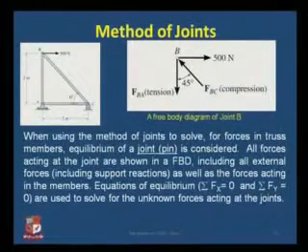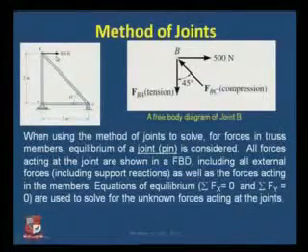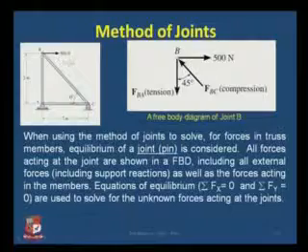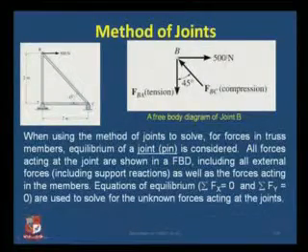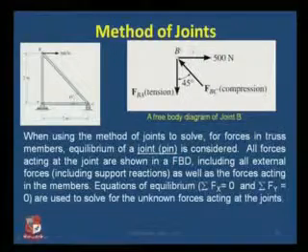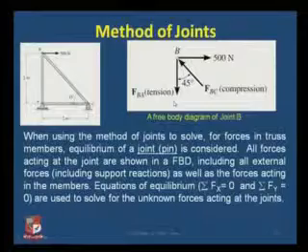and at joint B I have a force of 500 Newton being applied in the direction going away from the point B. So if I draw a free body diagram of joint B, I get something of this sort, where I have FBC under compression and FBA under tension by common sense.